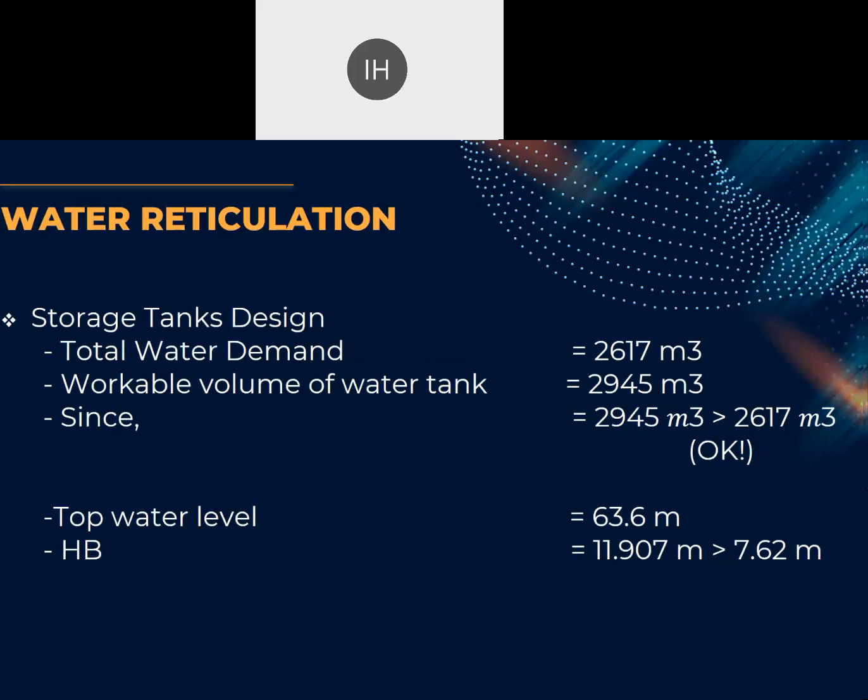Since our workable volume of water tank is more than total water demand, it is okay. Top water level equals 63.6 meter, and HB equals 11.907 meter, more than 7.62 meter.